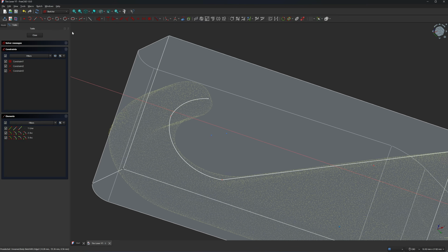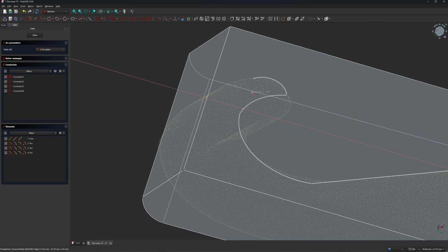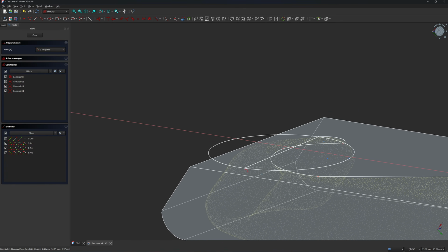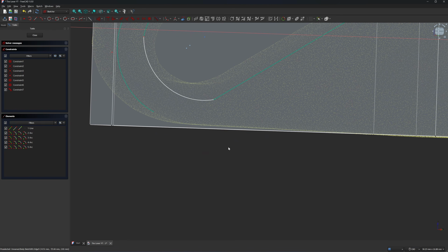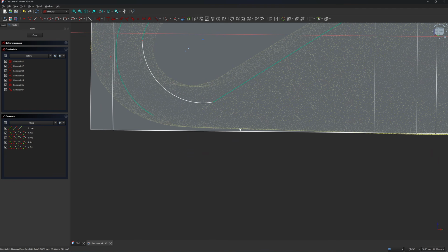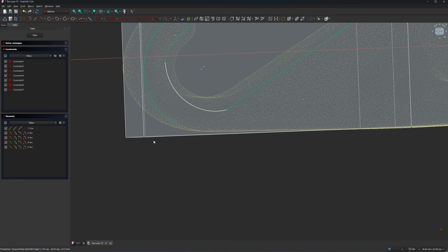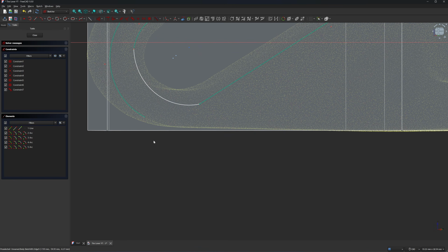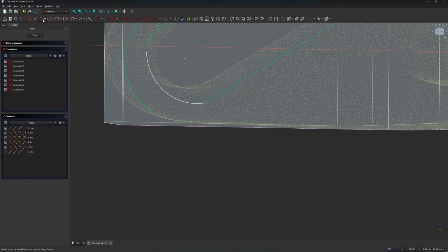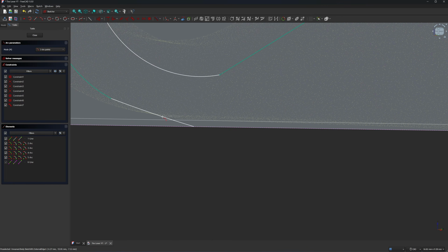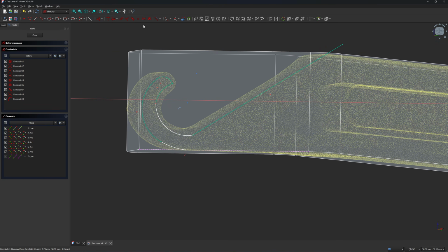Okay, next I'm going to create a third arc. Okay, the fourth one. Let's go up to about here. Okay, let me lock this and lock this. Let me tangent this to this. Okay, so if you look here, there's some slope angle on this face of the wall, but I want to put this side of the wall to the print bed, so I would just assume that this will be a straight line. I'm going to create external geometry on this edge and create another arc, go to this point. Okay, and next I'm going to close the profile.